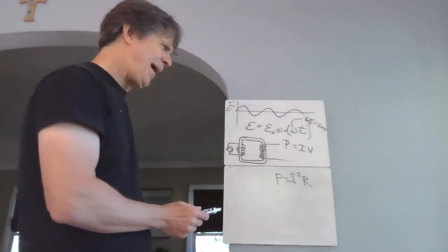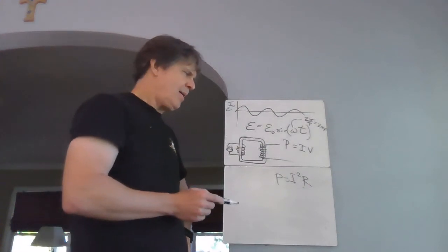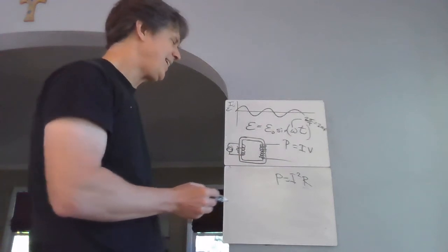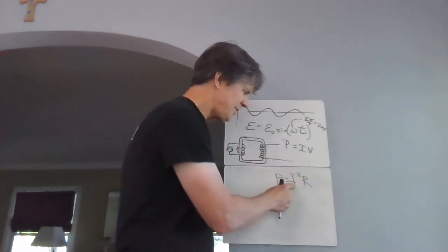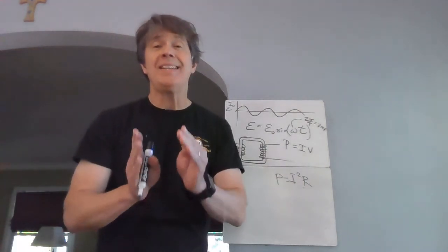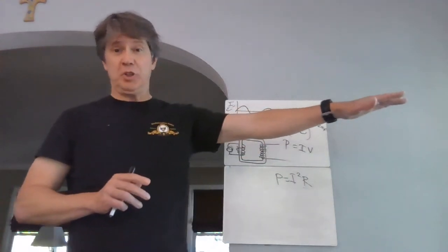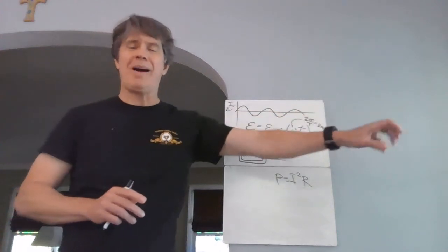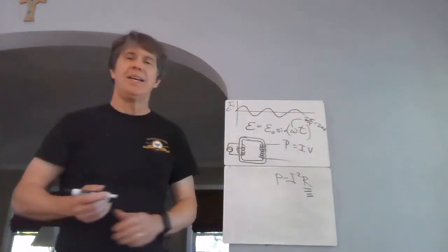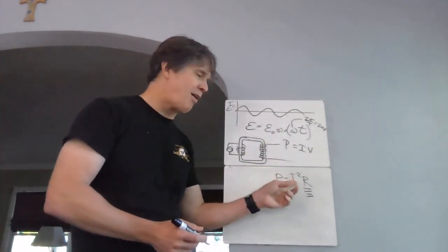So the power lines that you're sending it out on have a given resistance. But if you, I'm hoping I'm saying this right, if you have a smaller current, you're going to get a lot less power dissipated in the wire. I almost confused myself because I was thinking about the power that's trying to reach the ultimate end user. Somebody wants the electricity out there. They want their power. What you don't want is the power gobbled up by the resistance in the transmission lines. So by cranking up to a high voltage, you get a small current.